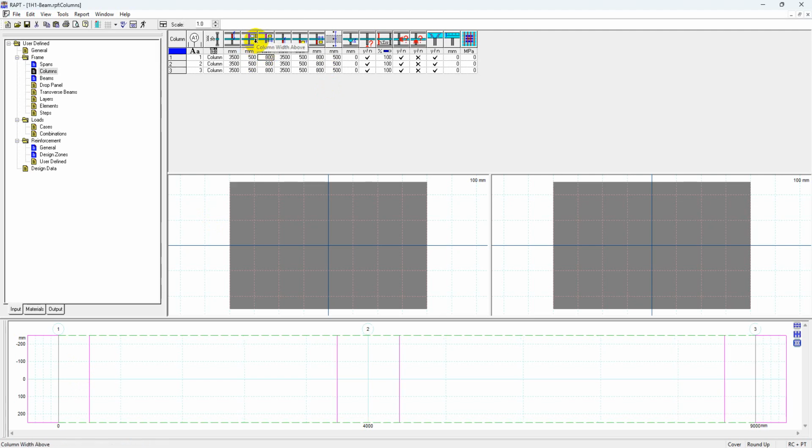We can have a look at this. This is the width in this direction. It is connected to the beam in this direction. This is connected to the beam width. This is the length from here to here, along the beam length, meaning that if we provide a higher dimension, the column will be oriented to the strong axis. So be careful when we input this. If we provide incorrect input here without proper inspection, we will have a problem when we do the analysis and the design.